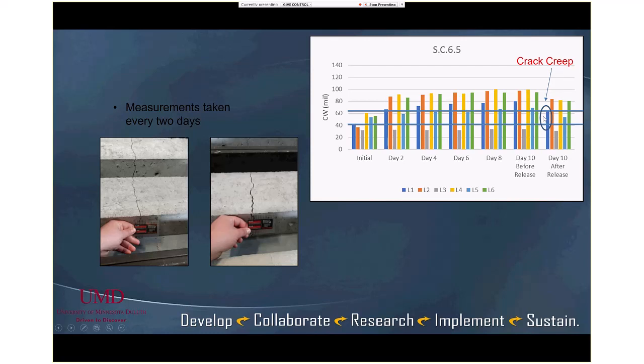We do not know whether the fibers that we have in the market right now are good for the pavement. That's a question, because those were not actually designed for the pavement. Those were actually designed for the industry slab, which definitely experiences a different kind of load than what fibers get in the pavement. So we might need to think about this.